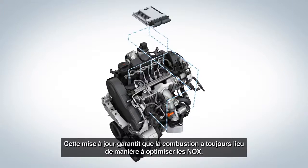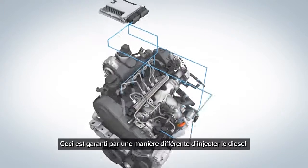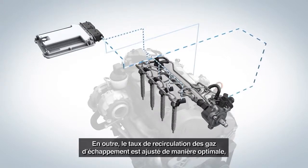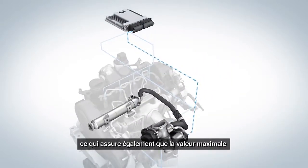The adapted software ensures that the combustion is always carried out in a NOx-optimized mode. This is ensured by a modified strategy of the diesel injection and a slightly increased pressure in the injection system at partial load. In addition, the exhaust gas recirculation rate is optimally adjusted, which also ensures that nitrogen oxide test limits continue to be met.